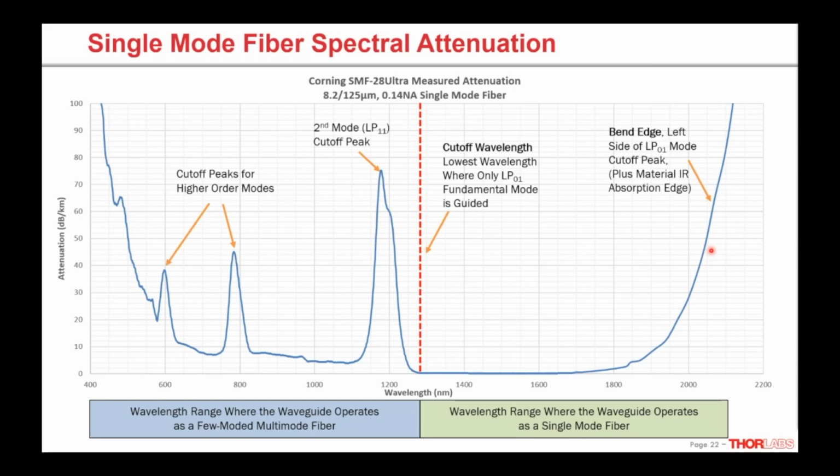When the light goes through a fiber, it's passing through glass along that whole multi-kilometer run. And silica glass, which we normally make optical fiber out of, starts to absorb light at a low level when you get close to 2 microns or 2000 nanometers. That's due to multiphonon absorption, as we call it, which is basically the molecular lattice absorbing those photons into vibrational energy.